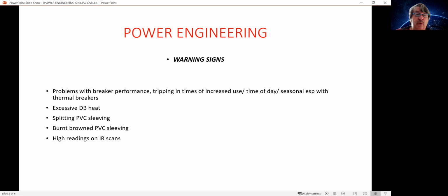And of course, with all this going on, if you are doing infrared scans, you're going to get hot spots just based on this type of thing. So you're going to find your cables are decidedly hotter than these devices that we're talking about here today: solid busbar, braided busbar, and different insulation levels are at a different heat. So they will be hotter to the scans, and you're going to have a look at those with some concern.